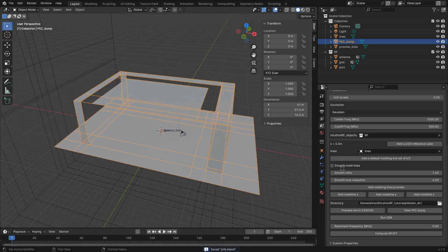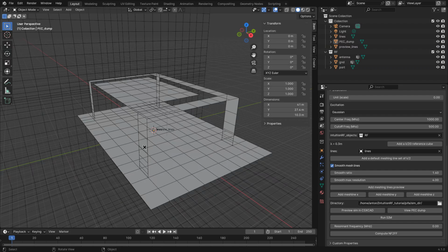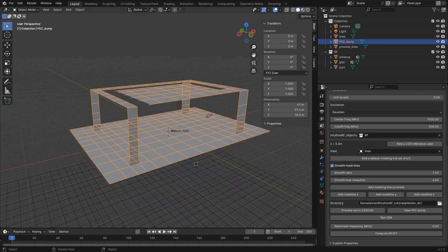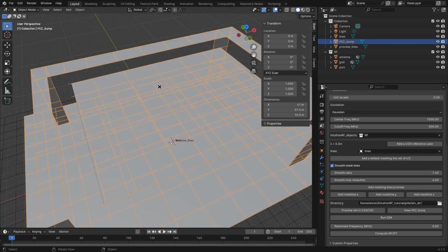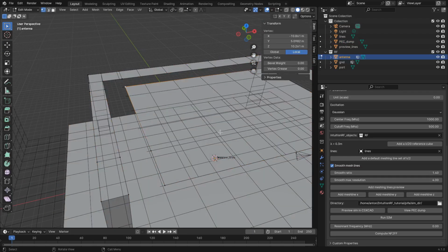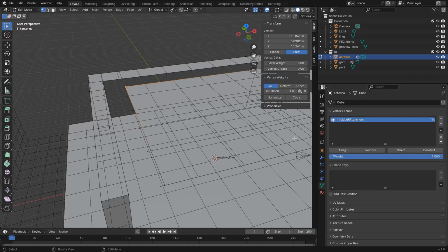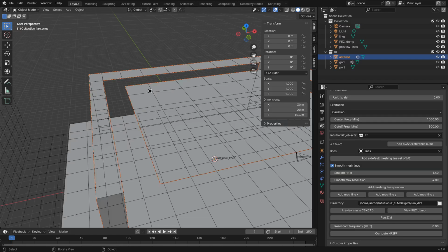Now we can add the smoothing back in. And so that's our perfect electrical conductor meshing. As you can see here, we probably lack an anchor here. Let's add it like this. Yeah, that fixed it.